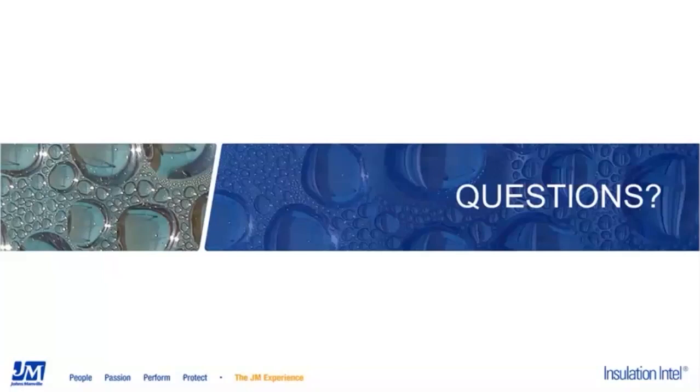Hi, this is Jim. I actually want to go back and just mention something about a previous question. Somebody asked what parts of the system need to be insulated, and Meredith or Kathi, I don't remember who it was, said the whole thing. And that's absolutely true. However, there are times when something isn't insulated or can't be insulated, or maybe a valve is getting constant maintenance, so they choose not to insulate it and accept the condensation that's going to likely occur on it.